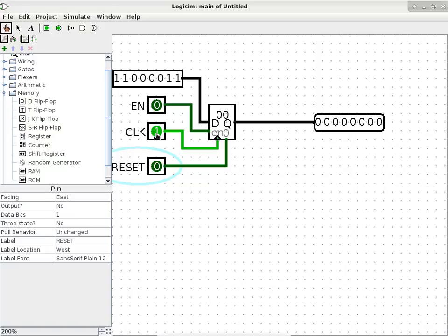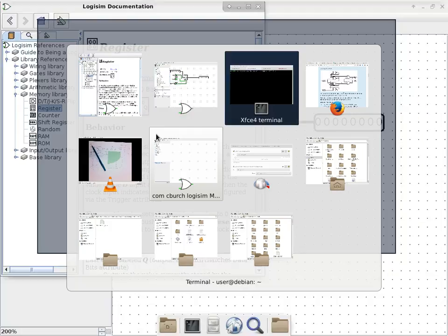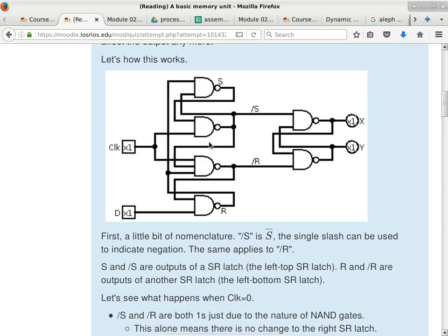Okay, let's go back to the slide in the previous one. Let's go back to the browser. This is a good slide. So what is happening when you're quote-unquote clocking too fast is that when you have a new update cycle, these gates have not completed all the operations yet. And then you're trying to refresh it with a new state, which basically means it's undetermined. It depends on how slow the circuit is, and on what the new input is.